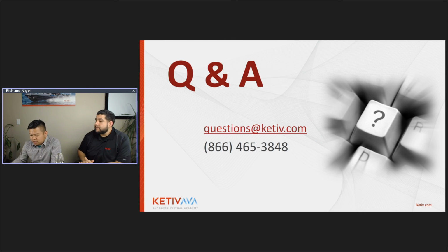Yep. And then it looks like I covered two more questions here. This one came up twice. Can I do a crop and a break in the same view? Ooh, that you can't do. Yeah, that comes up a lot in support too. So just to reiterate, you cannot apply a crop and a break, or a slice and a crop. Any of those functions that Rich did on those views, I think I've tried them all to see if I could do two at once, and you can't. You've broken Inventor trying to do that before. I probably have broken Inventor.